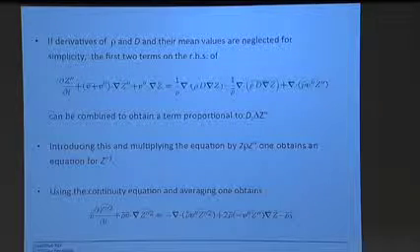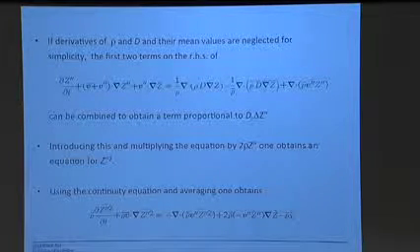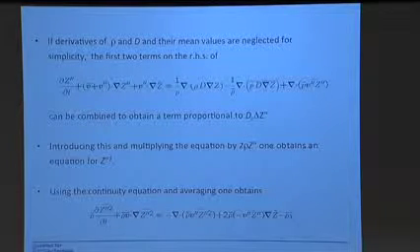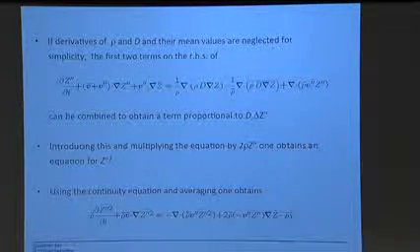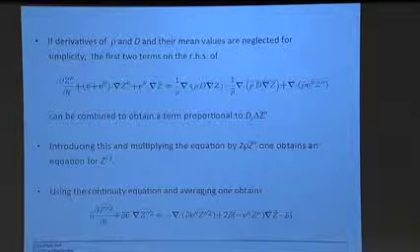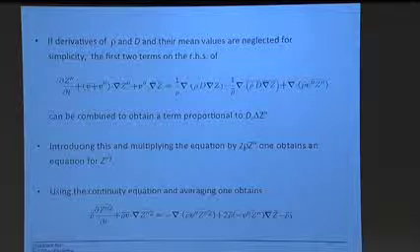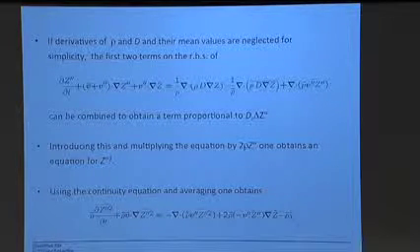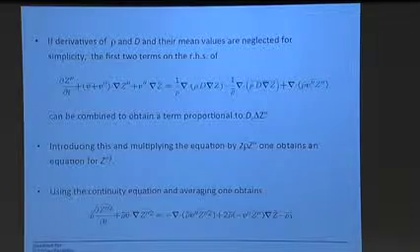And you see an old friend in that equation. Production term, that's also a good old friend, but the dissipation rate, okay? Here we see the dissipation rate appearing again. And now, it kind of makes sense, what we talked about earlier, what does the dissipation rate do? You have, let's say, a mixture fraction profile that looks like this.